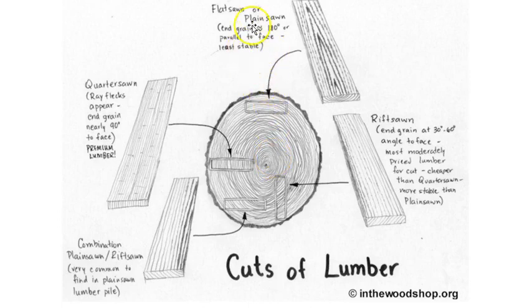So here at the top we have flat sawn or plain sawn lumber. This is where the end grain is cut, or the cut is made, at approximately parallel with the face. So it's the least stable cut. That's very important, that fact. Least stable, and we'll zoom in and see some pictures of these. But this is the cut that would tend to cup and follow those rings.